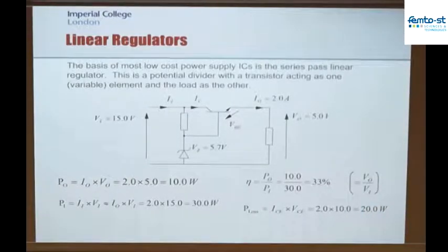Well, actually, it really just comes down to there's a certain amount of power you can pull out of the source based on the basic requirements and fundamental principles we saw in the last slideshow. And so if I can generate 10 microwatts as an absolute limit from a particular harvester, and my electronics is only 20% efficient, well, then I can only get 2 microwatts useful into the load, and I might need more than that. So the efficiency really from a harvester perspective is not about thermal management, it's not about maximizing battery runtime, it might be simply about making the device work at all.